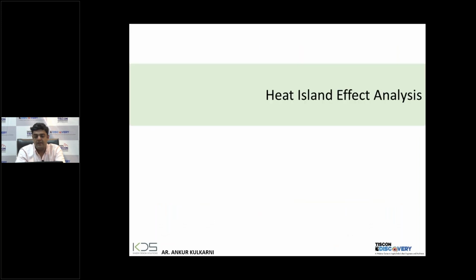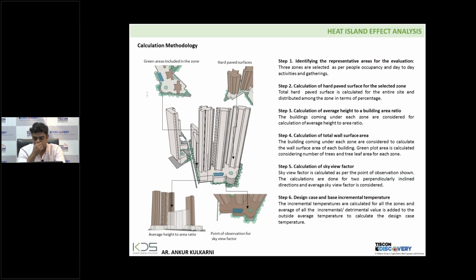That's very important. Then yes, heat island effect studies. This is also very interesting and important. The idea is that the Ministry of Environment and Forestry (MOEF), as well as the high-rise committees in Mumbai, demand that your newly proposed development should not increase the heat island effect there. Whatever the ambient temperatures were previously, make sure that you are close to that, more or less. At least 10-15% up or down is acceptable.